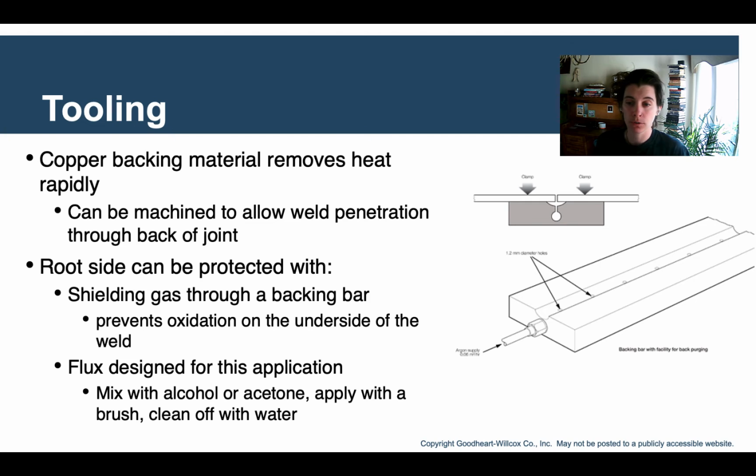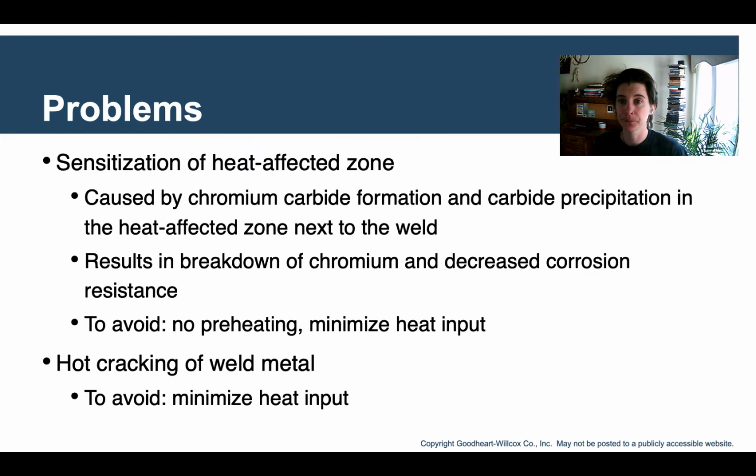There is also flux for stainless steel, and you mix it with alcohol or acetone, and you apply it with a brush on the back side. So again, that is just protecting the back side from oxidation and stuff to get a good weld.